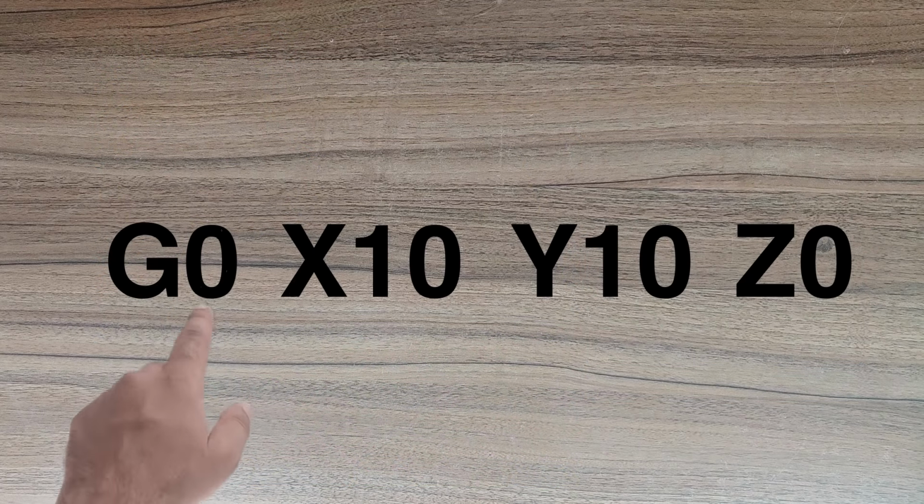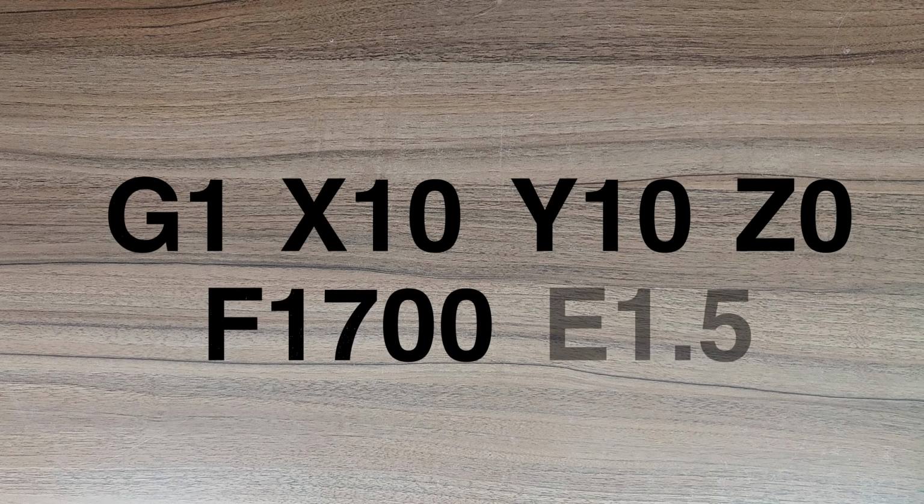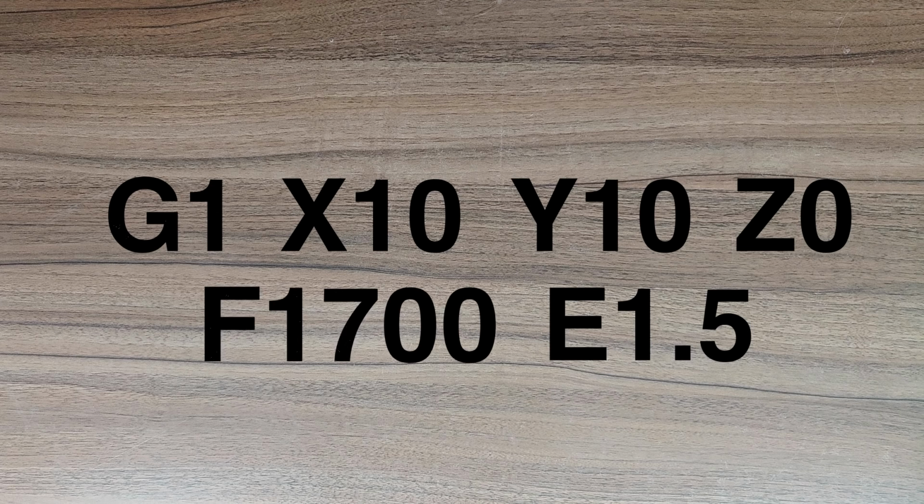The next command is G1. This command prints a straight line according to the parameters you provide. Just like G0, you need to provide the X, Y and Z coordinates and also the speed at which to travel and the amount of filament to extrude. Now, the E parameter here works differently for different printers. It could either refer to the actual volume or to the length of the filament to extrude. For my particular printer, which is a Prusa Mark III, it's the length of the filament to extrude. And the F parameter here is the speed of the nozzle in millimeters per minute.